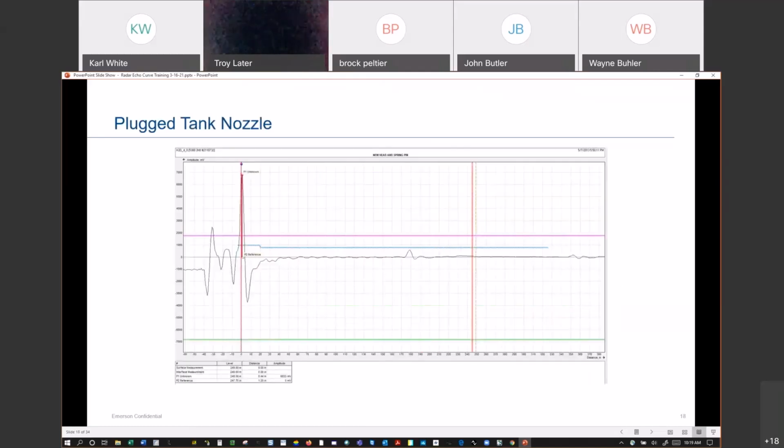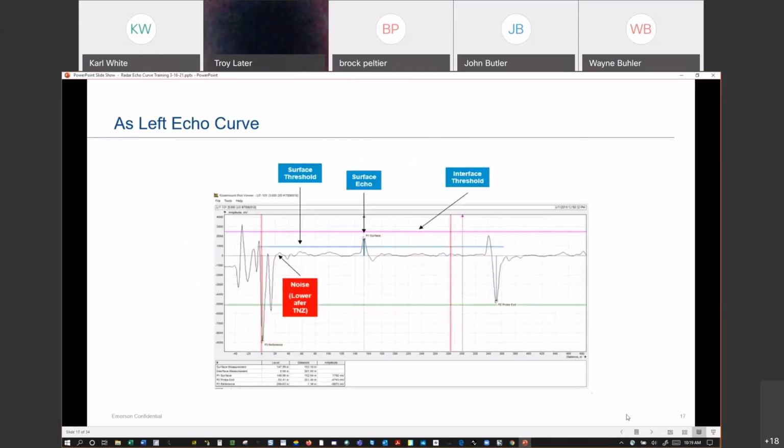And so John, just to show Wayne a couple of things that you and I look at. I look at that reference pulse, usually the first thing I look at, and I make sure that it's at or near zero. If I were to pull these up and look at a reference pulse and it's at 8 inches, it's not at zero, then I know you picked the wrong probe type.